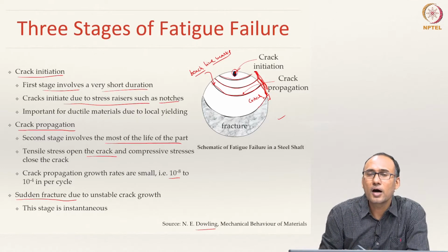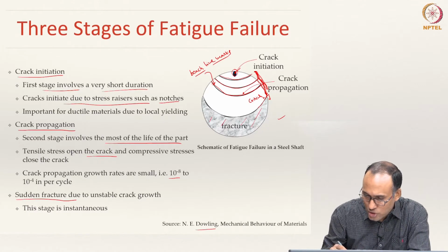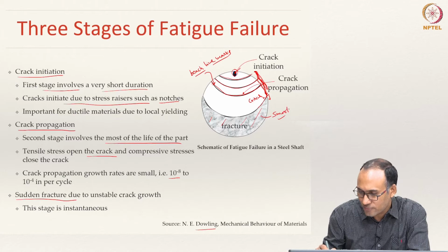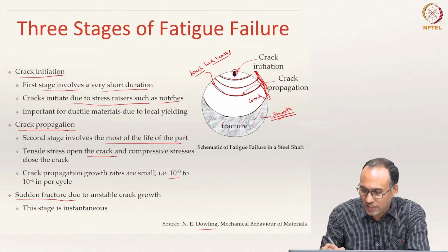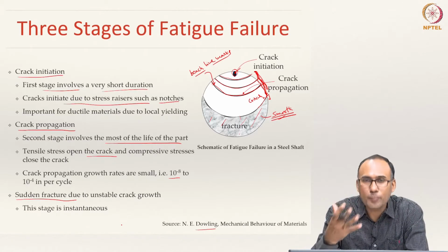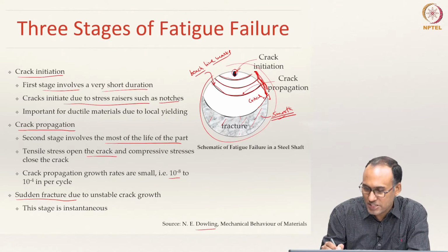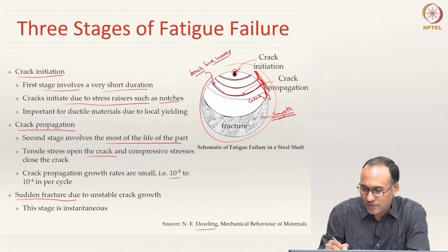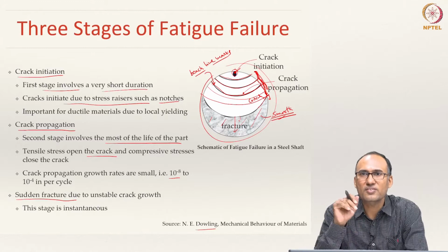in the case of our module in fracture mechanics, and then you will see the fracture surface to be a relatively smooth fracture surface. That means until now you have these beach line marks and suddenly you do not see the beach line marks. If you see a failed component and if you see features like that, so there is a point from which these beach lines are coming, that means that is your crack initiation site, and then after a certain distance these lines disappear and suddenly you will have a dimpled surface.